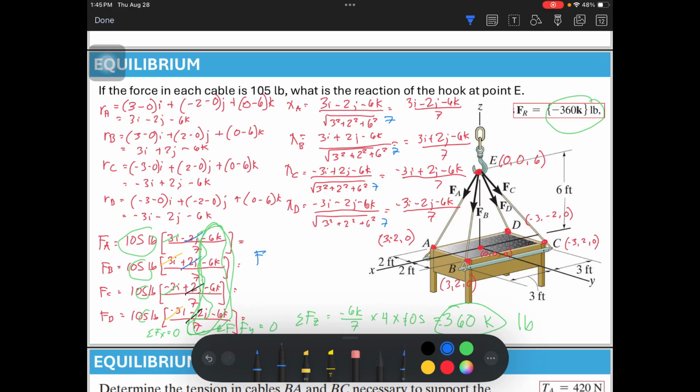Our resultant F is equal to the square root of the squares: Fx is 0, the summation of Fy is 0, then you square this, then take the square root, so FR equates to 360 still. Negative 360, where am I? 360, yeah, 360. When you use the Pythagorean theorem it becomes positive because you square it, right? But when you get the angles, it is still downward.